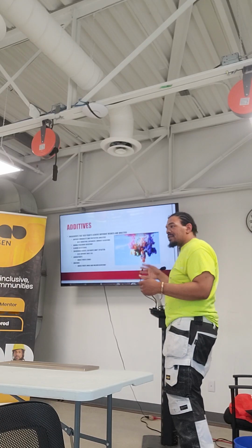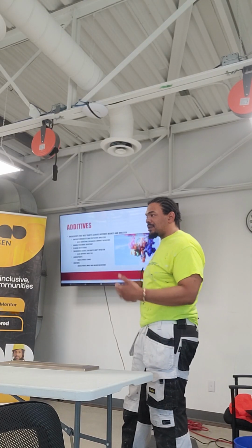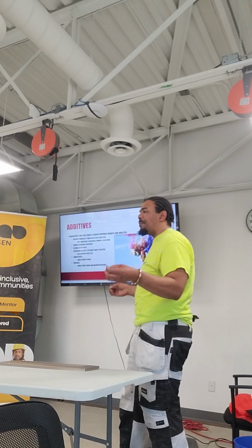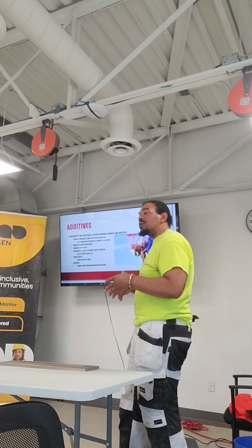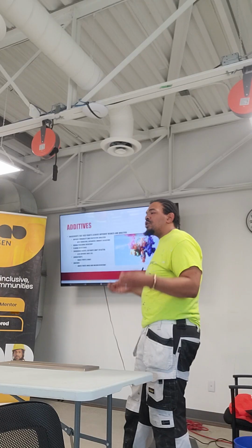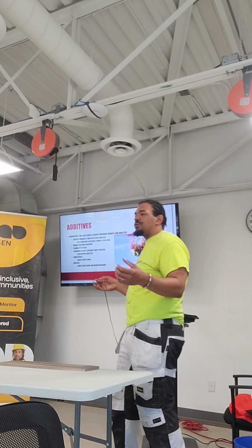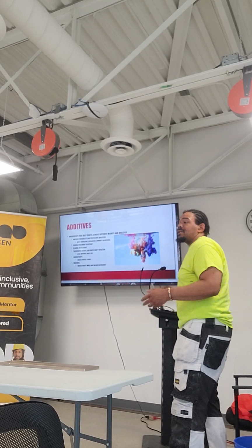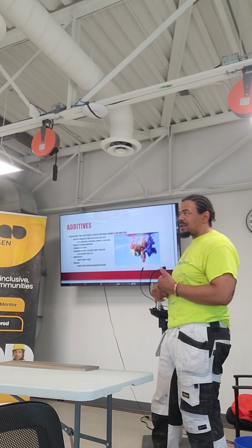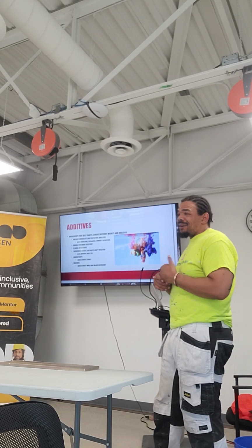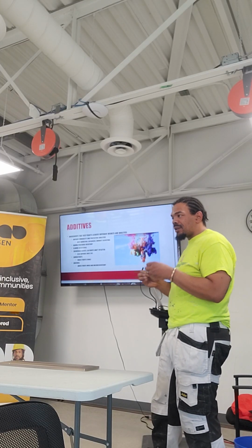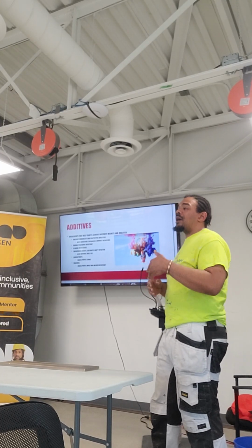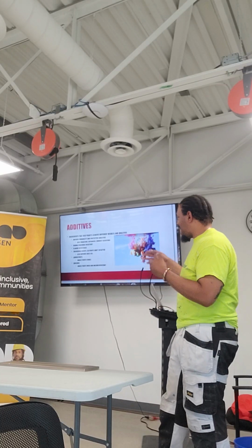So as we go through it, there are certain additives that they put into an acrylic that's designed to go on masonry, and it's also designed to go on drywall, and it can also be used on metal. They'll put more additives into that material, which makes it more expensive also, but it's over-engineered, and what you get in return is higher value because you can do more with it, right? Whereas you have some latex paints that are only designed to go on previously painted surfaces, so only for repaints, really not much outside because of the stretching factor on latex. It'll pull off a surface. It's not as heat resistant as acrylics are. So that's why acrylics are designed better for outside because of the additives that they put in it, right?